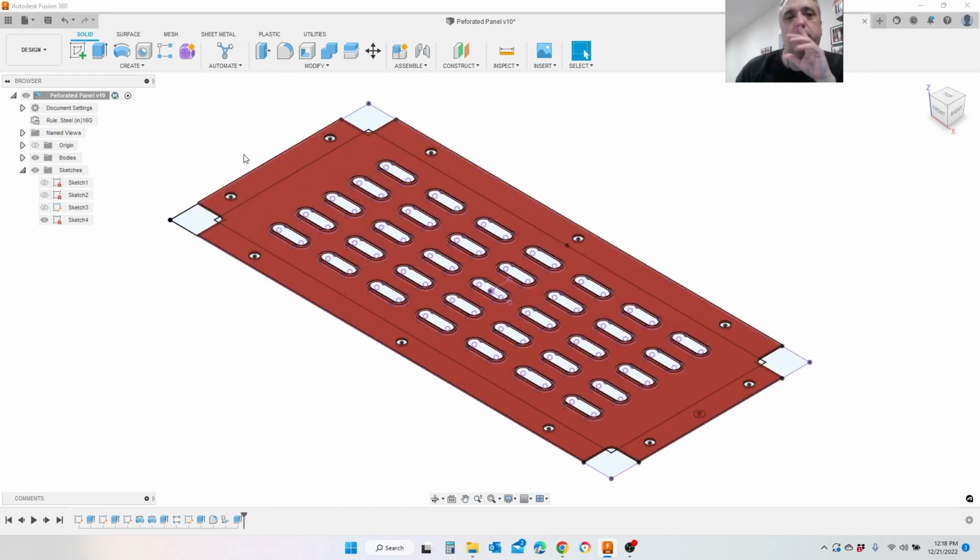One thing to also keep in mind, if you're doing sheet metal design and you have multiple sheet metal parts within a design, be sure, and it's not the case in this model, before starting the actual design of it, to create a separate component of it. Because if you have a sheet metal rule up on higher level components and you create another component underneath it that is sheet metal, it'll have problems doing the calculations between the two because they're within the same component.